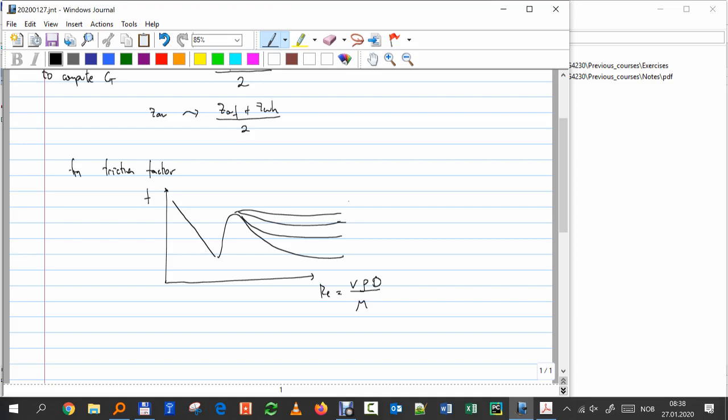We have something called relative roughness, and that is the roughness divided by D. If I have my pipe, it typically has some roughness, that I simply measure, that E, simply the roughness. I think they used sandpaper by that time. They glued sandpaper to the wall of the pipe.